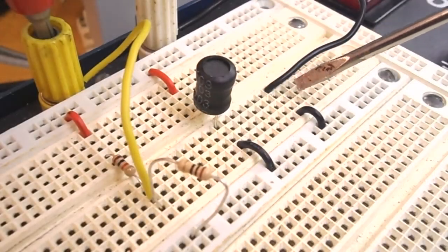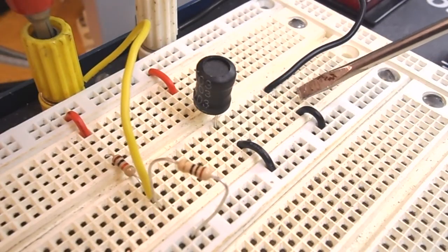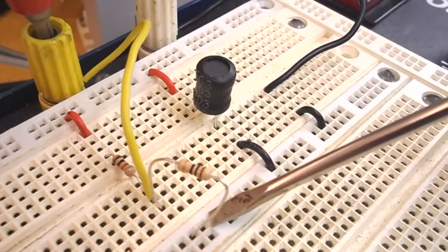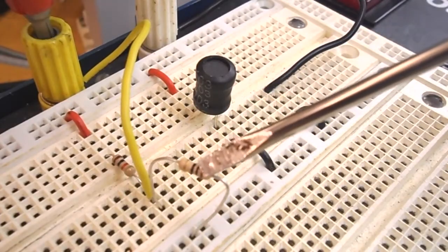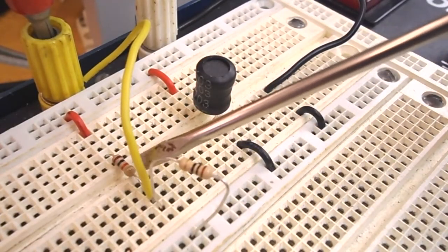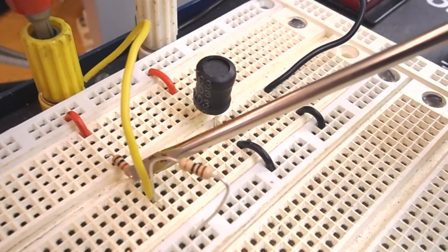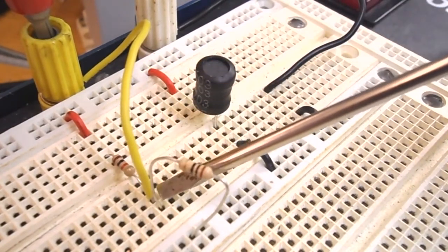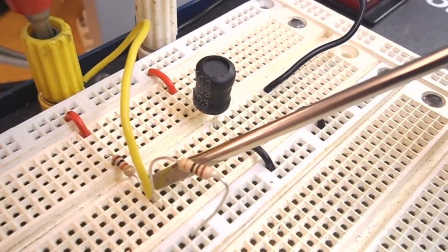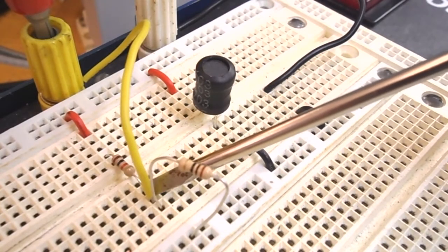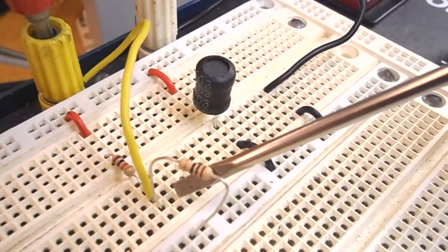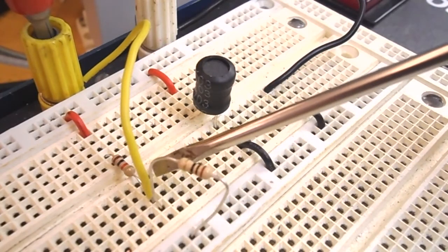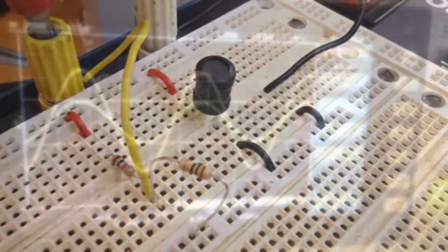I've now replaced my sensing resistor with a little short jumper, so that now brings in ground to the entire ground bus. And I've put my sensing resistor in series with my 1K ohm resistor and moved channel 2 to see the point between the 10 ohm resistor and the 1K resistor. So it's looking at the voltage across the 10 ohm resistor, which represents the current going through the 1K ohm resistor.